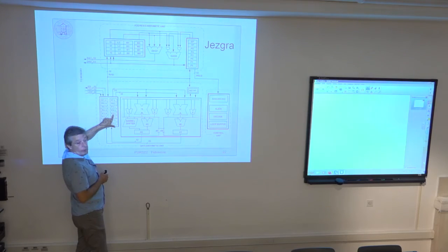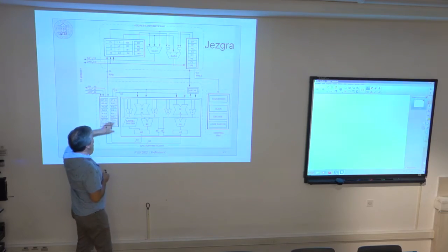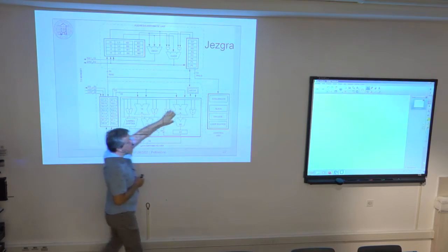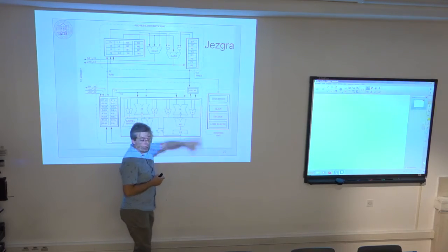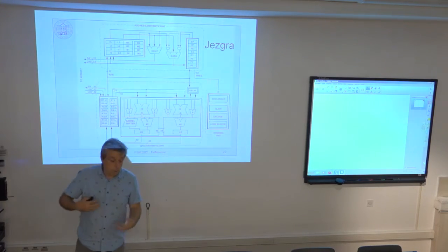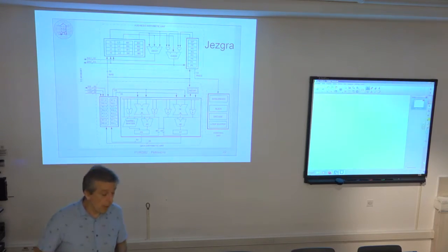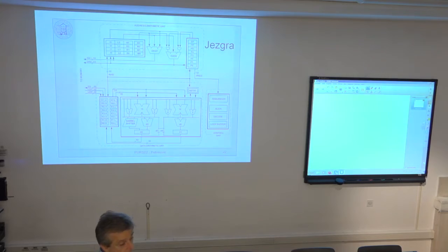By R3 low. So R2 high multiplied by R3 low is done here. At the same time, R3 high and R2 low are multiplied here. So that is the way it can support two multiplication instructions in the same cycle, because it has two 32-bit buses to take actually four 16-bit values as arguments for multiplication and accumulation.